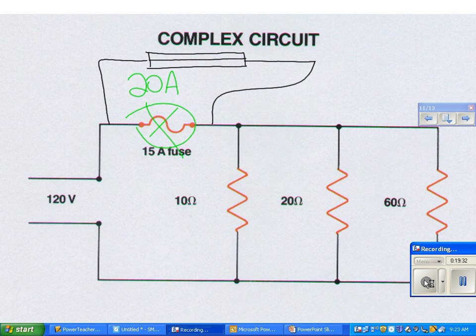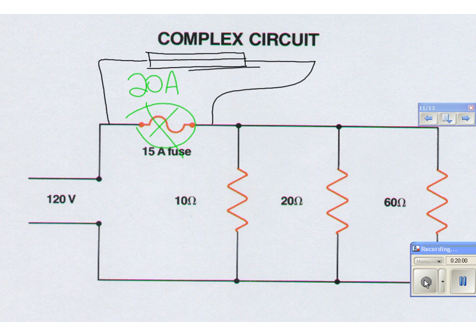So I've got two pieces of metal globbed together, heating up, and expanding at different rates. What will my bimetallic strip do? It would come apart if it could, but it can't, so it won't, because it's all globbed together. So it's stuck together, and it can't come apart. So what will it do instead? Imagine this one on the bottom gets longer than the one on the top. What's it going to do?